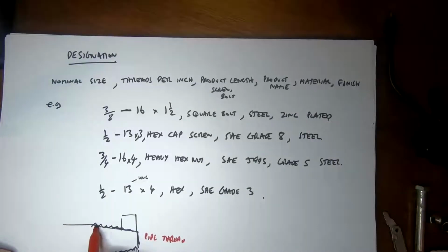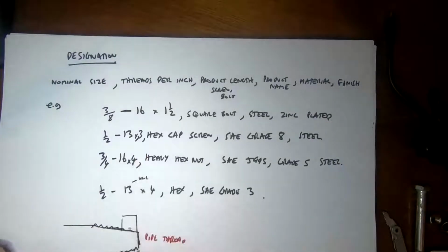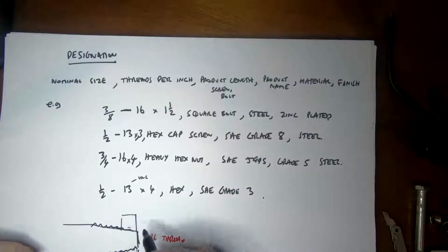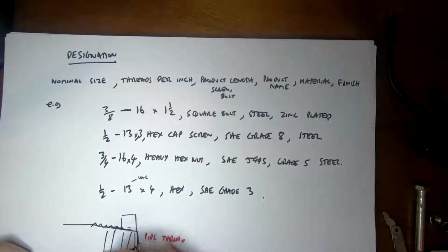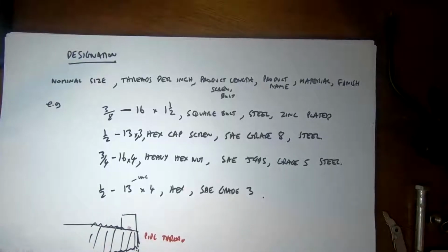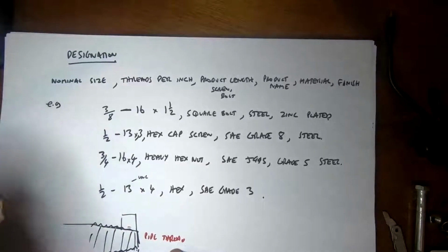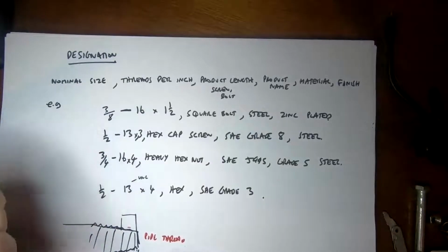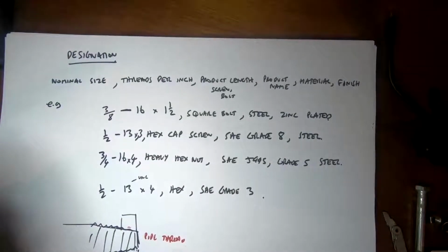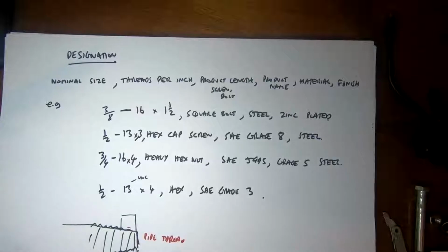The specifications for the threads actually tend to be the same for the nominal diameters, so it'll be 13 threads per inch, 16 threads per inch, wherever it'll still be there, but there is a taper to these standard pipe fittings. So that's another very useful one between the pipe and the UNC and UNF. That covers most of the applications we'll come across, and we won't use the pipe too much, but it's good to be aware of that one. Okay, so that's it for now.